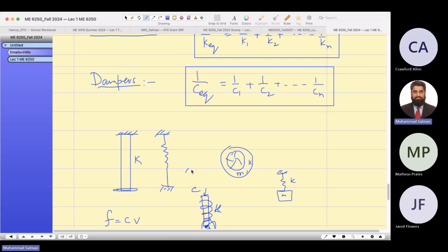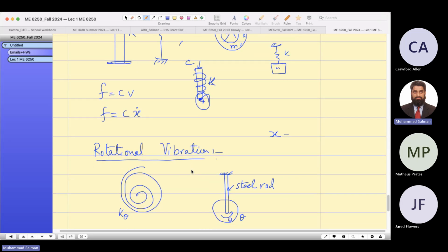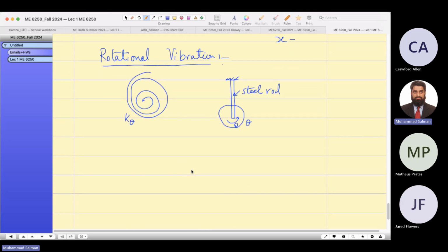The bridges have their own natural frequency, and if you start deflecting those bridges at their structural resonance, then that resonance will increase the amplitude of vibration, which we don't want. We never want any machine to vibrate at its structural resonance frequency, because I'll teach you how to find the resonance through the mathematical equation.